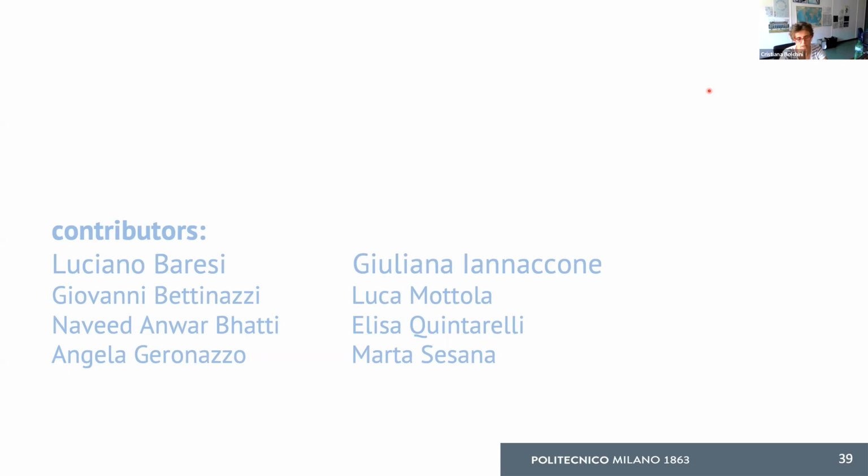Or if these elements are going to be set into place because they're going to stay there, because you're doing actually the final smart building. So the cost of technology for sure has an impact, as well as the kind of technology. If you do some kind of monitoring for just a limited time space for assessment, you can easily use wireless modules as the one we had in place. If you are doing something that's going to be part of the smart building, wired sensors are possibly a better choice, because once you put them in a certain place, you are not going to move them.